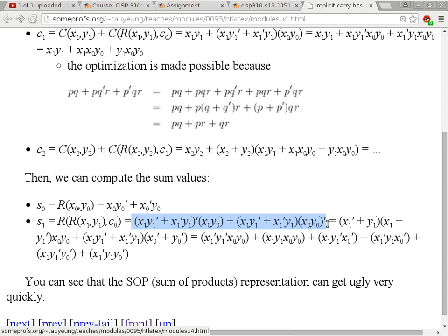So when you look at the adder on the actual silicon die, it's not like a block of Legos. It's not all clean and the same shape, just piled up like this. The adder, when you look at the actual transistors and how the lines are routed, is a big mess. It is a big mess because they need to do it as quickly as possible. If you do it using carry ripple, this way, your process is going to be a whole lot slower, because every time you add 1 to a 64-bit number, this end will have to twiddle its thumb and wait and wait and wait until all of the previous full adders have settled down. But doing it this way is a whole lot faster.